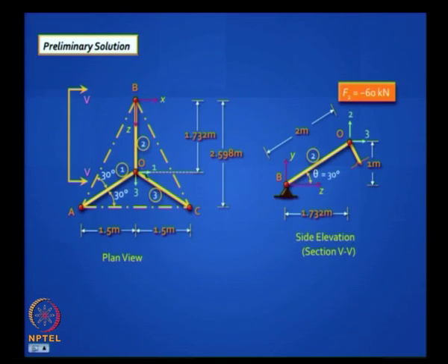And you can figure out how to locate these dimensions, because you are given this length is 2 meters. If this is 2 meters, this angle will be 30 degrees because this is 2 and this is 1, so 1, 2, and this will be root 3, so this is 1.732. So these dimensions can be worked out, okay, that is the first thing you need to do.